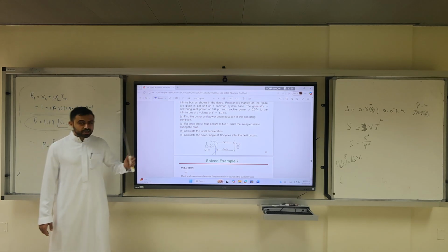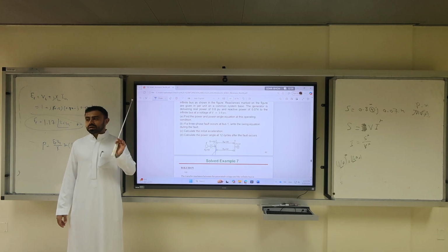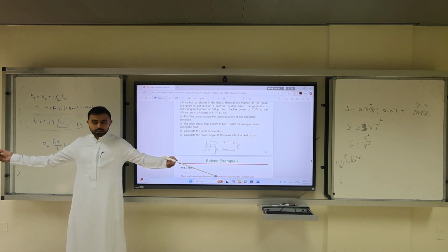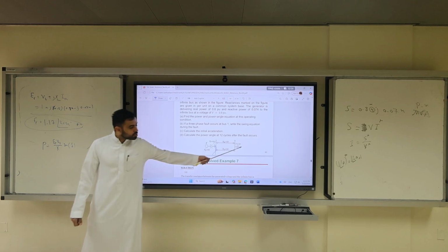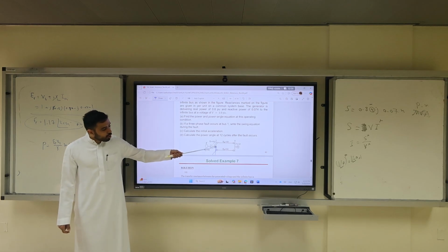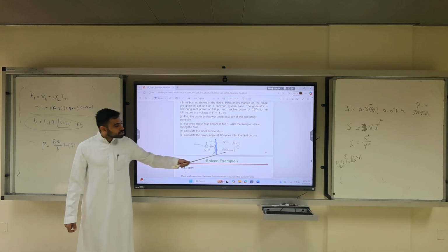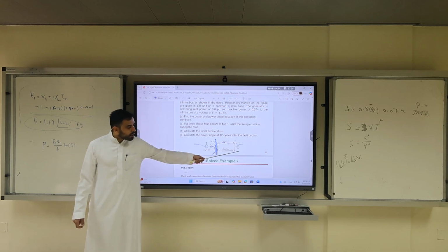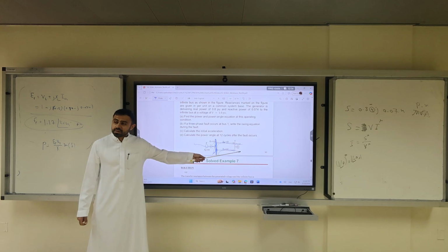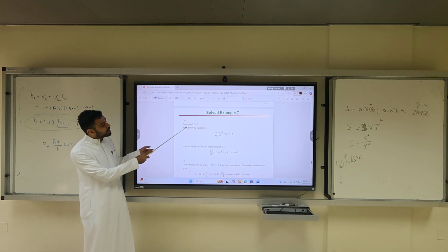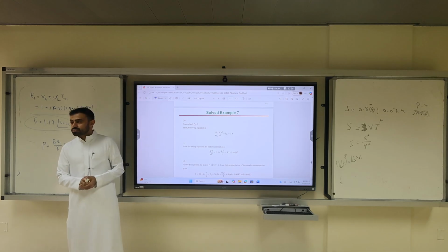So if a fault occurs, here's the thing, rule of thumb: if a fault occurs at any point, you assume that all the current would go into the fault location. The contribution comes from the generator, and the contribution comes from the infinite bus, all the way to the faulty bus. So bus 1 would become like a magnet. It will take all the current. If it takes all the current from the infinite bus, would it harm the infinite bus? No. Would it harm the generator? Yes. That is why we have PE during the fault to be 0.